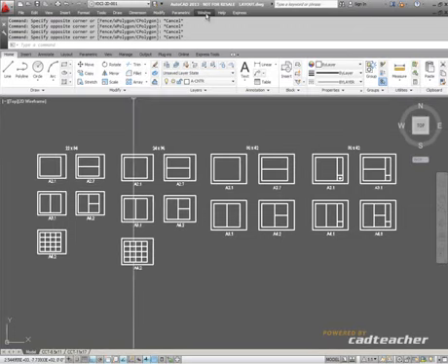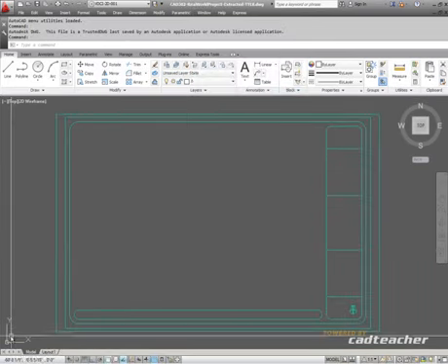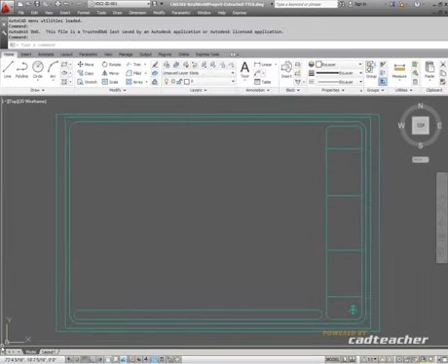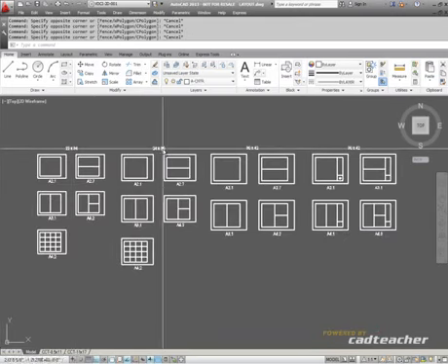So what we need to do is go into our extracted title block and figure out exactly the size that that title block was originally, so that when we put our deliverable product together, we can bring our building into model space and our title block into paper space at 1:1. So what I'd like to do first is to create a new drawing file that will again indicate the 1:1 sizes of the three standard sizes of sheets, being 22 by 34, 24 by 36, and 30 by 42.